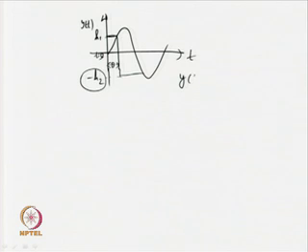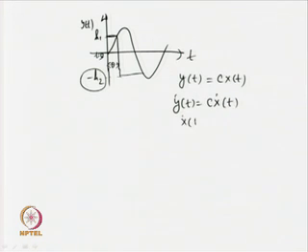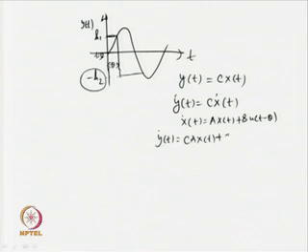output signal. The output signal is given by y(t) = c x(t). Thus, the first derivative of the output can be expressed as c x dot(t). Further, we know that x dot(t) is equal to a x(t) plus b u(t minus theta). Then, y dot(t) will be equal to c a x(t) plus c b u(t minus theta). So, now from here you can see that c b becomes 0 very often for some types of processes. So, in that case y dot(t) will be simply c a x(t).